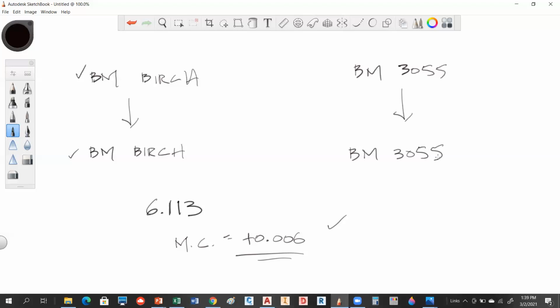Do your loop first. Solve your misclosure, and the misclosure on this one turned out to be a plus 0.02 feet. So if anybody did those, that's what you should come up with. Check your loop misclosure first, and then come back and do your side shot values. That was the one thing I noticed the most on people that had problems with the quiz. They tended to do the loop right, and then they blew the side shots.